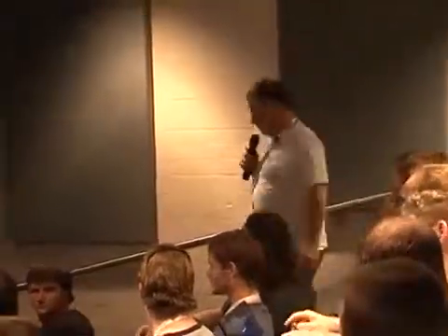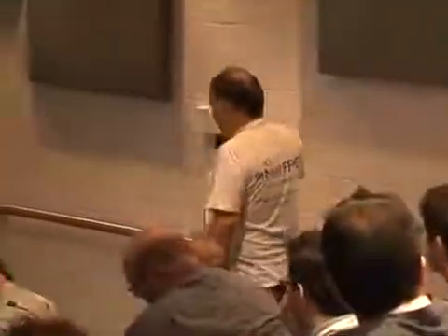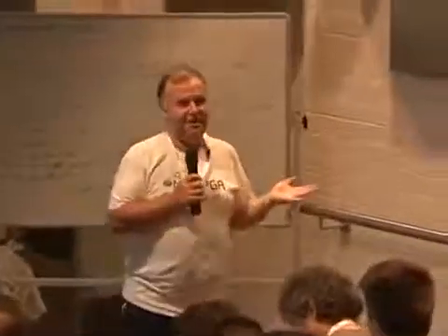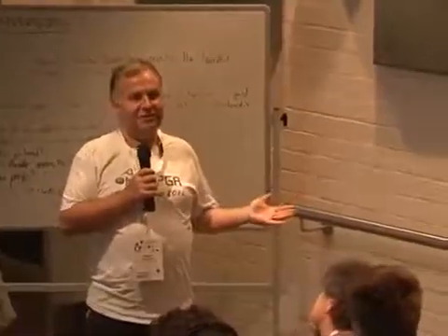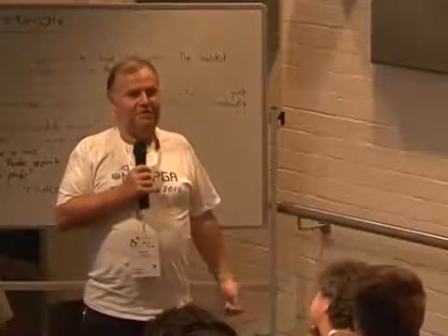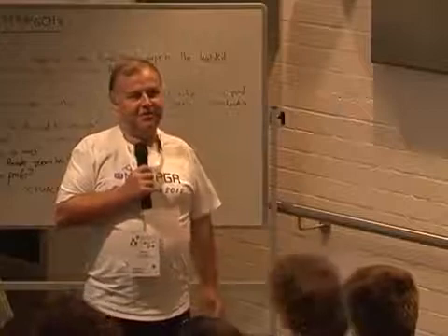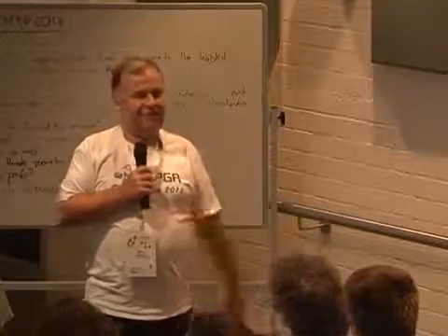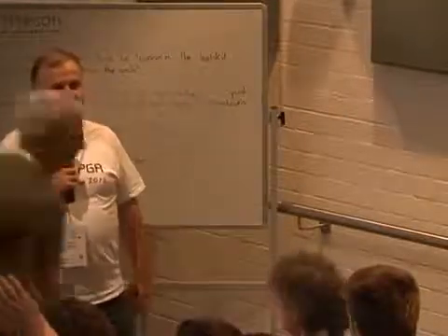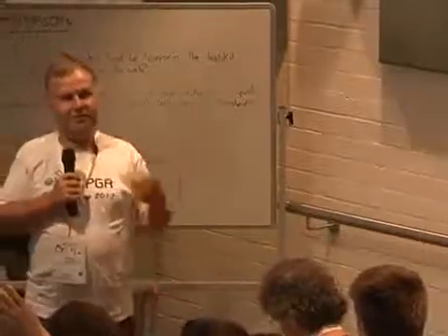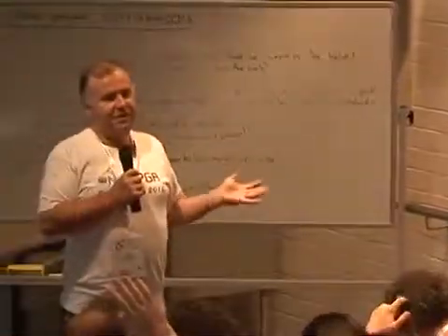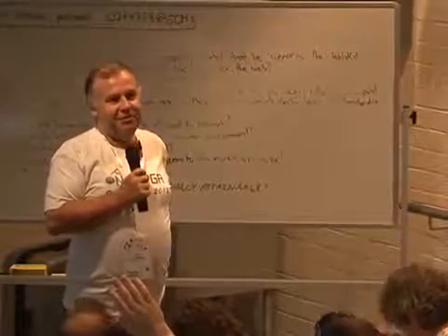Well, I'd be really wary of calling any of the people in the FPGA team twits, but I've never seen anything that uses the debug connector. The debug connector is just there, and I've never seen a single reference to anyone doing anything at all with it in terms of presenting information. So they may have used it internally just to check that things are working right, but it's got ground, so there's 6 ground pins. It's got 2 clocks that go to the FPGA. They're called clocks, but I think they're no different to any other pin, and there's 32 other pins.